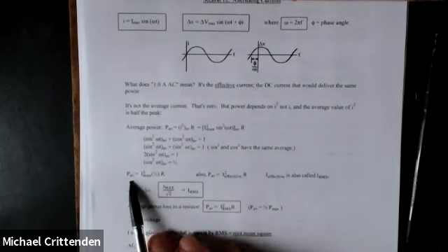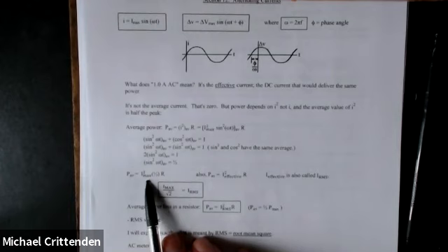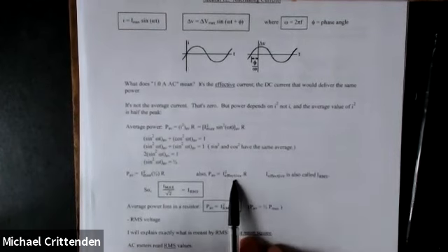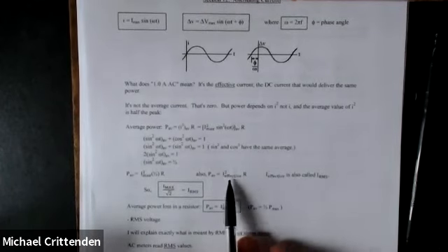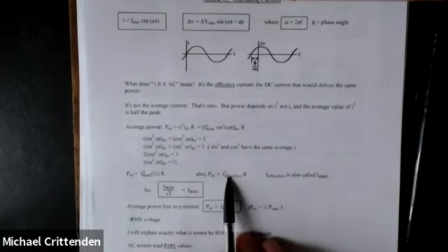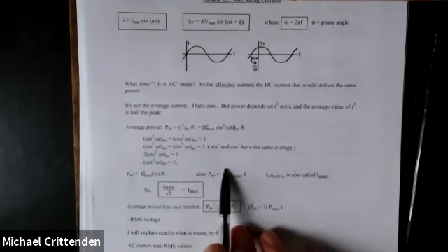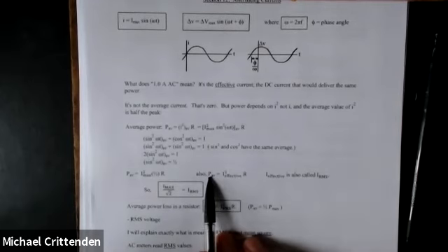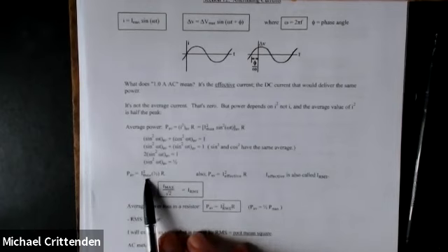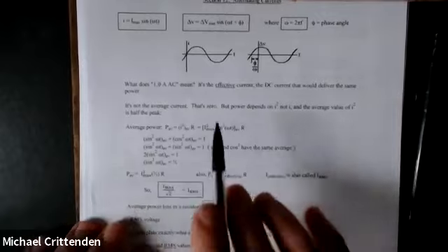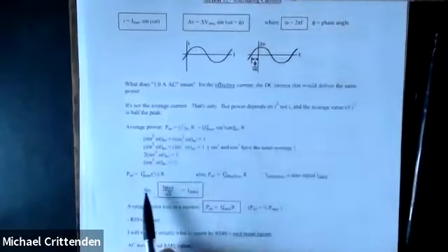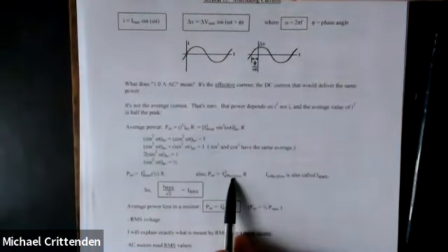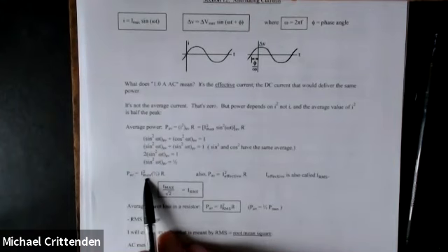the power is equal to the square of the effective current. You know, if it was DC, it would just be power equals I squared times R. That equivalent DC current squared times R is equal to the power. And we can see here that that relates to the amplitude of the current, the peak current, right up here at the top. I squared effective equals I max squared times 1/2.